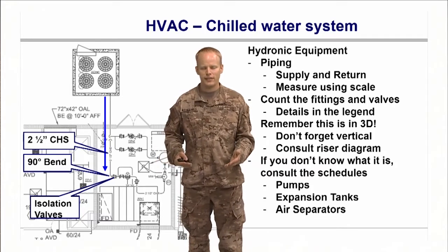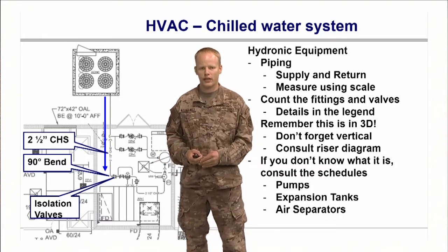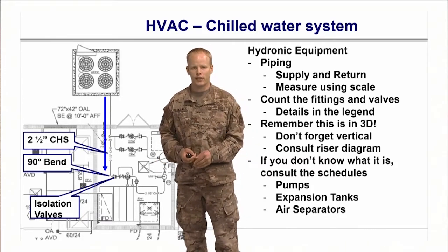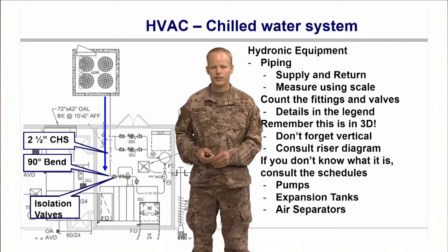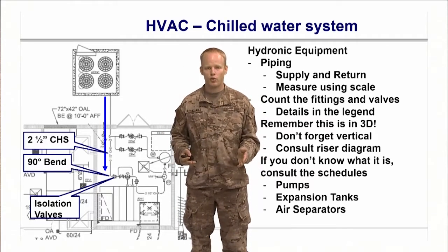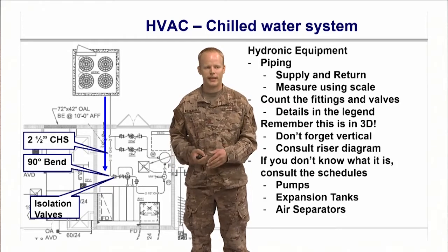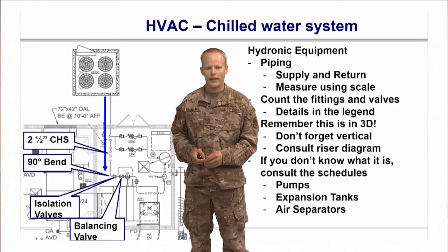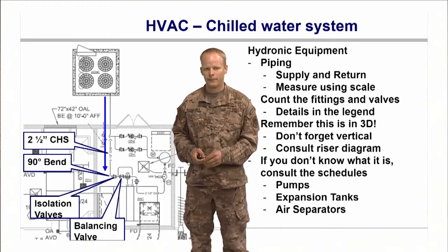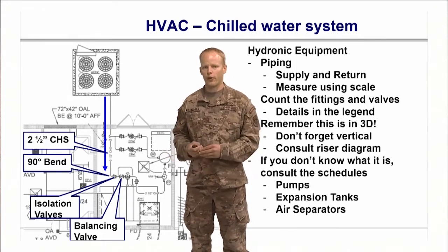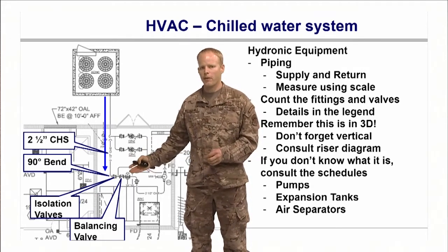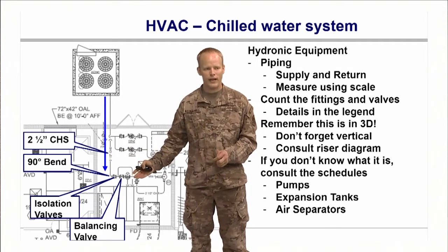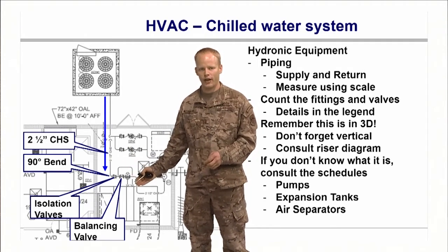When designing this, hopefully your mechanical engineer has put in isolation valves on either side of your pieces of equipment. This allows us to do maintenance without taking down the entire system. So we have our isolation valve. We then have a balancing valve in here. For this system, it may not be as critical to have a balancing valve as we only have one air handler on here.